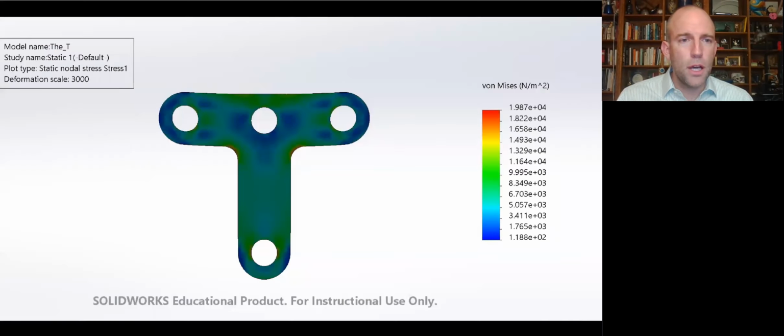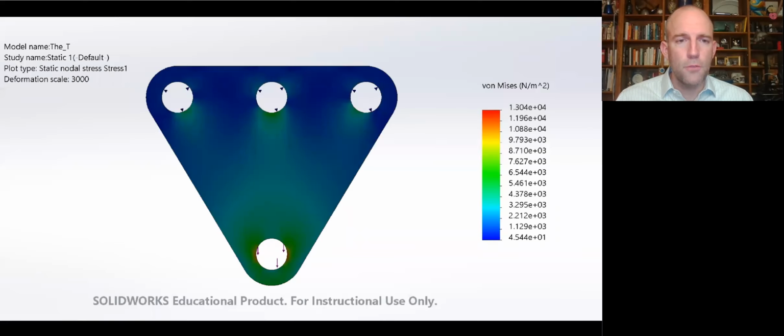So here's an example of a case where we've put these holes on very springy supports. I think it's maybe a centimeter of deflection there. And if those pegs are super springy, then now you get closer to that 1/3 force upwards at each hole solution. And here's another version where we've filled in this material so that it's like one big plate, and you can see that, yes, you have lines of stress going from the center hole at the bottom to all three holes at the top. And it will turn out that we have a really similar 1/3 F up solution in this case too.